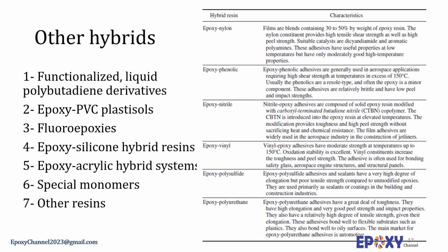The epoxy-PVC plastisol type is a mixture of a plastisol grade PVC powder, primary PVC plasticizers, for example, dioctyl phthalate, a liquid diglycidyl ether bisphenol A resin, thickeners, stabilizers, surfactants, and other additives. The epoxy-PVC plastisol adhesives are soft and flexible after cure. Their important properties are their low cost and long-term toughness and adhesion, as well as adhesion to oily steel.